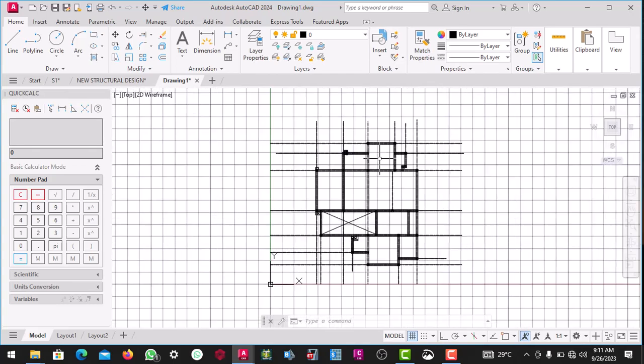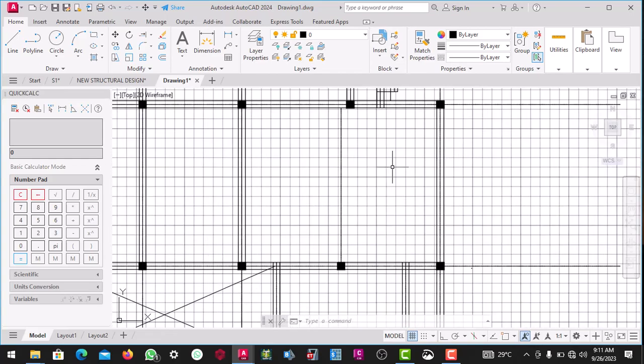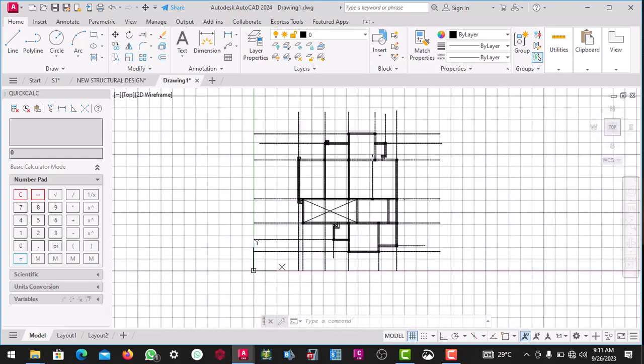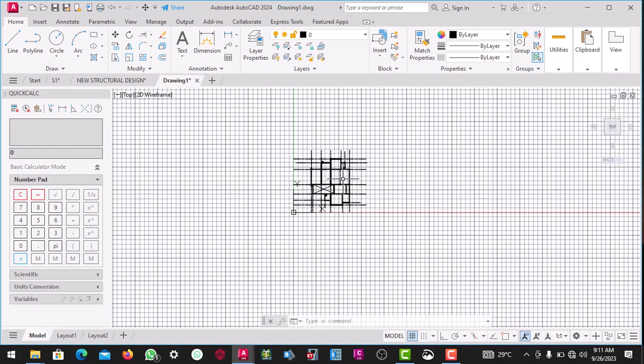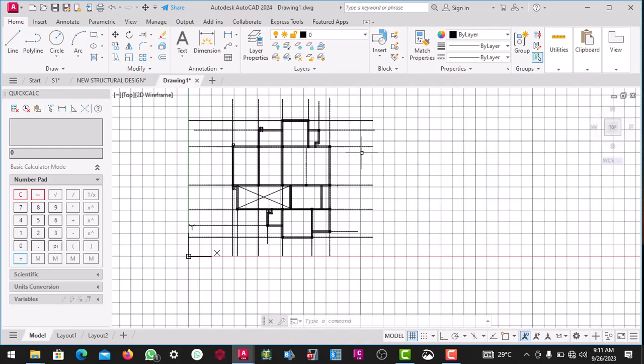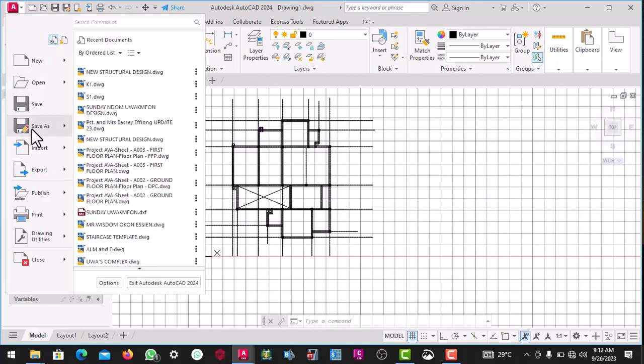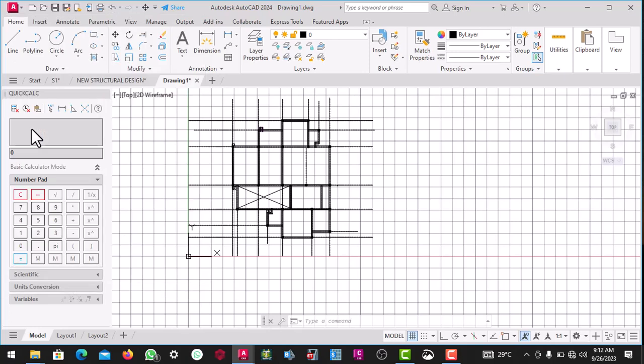And when you are saving any drawing in the DXF file, you don't save it in a sheet that contains other multiple drawings. You save it in a fresh sheet that does not contain any other drawing in it. Okay, so the next thing we will do is to go to save. You click here, go to save as, click on save as.